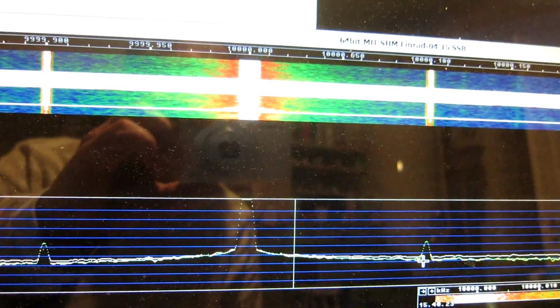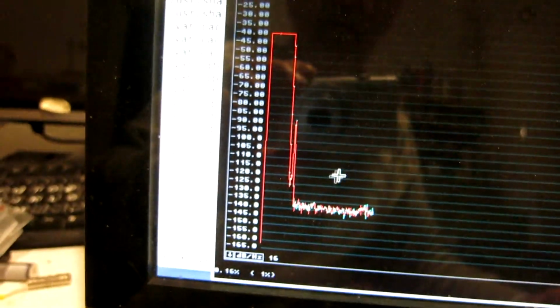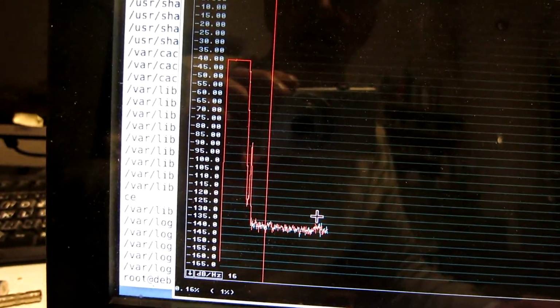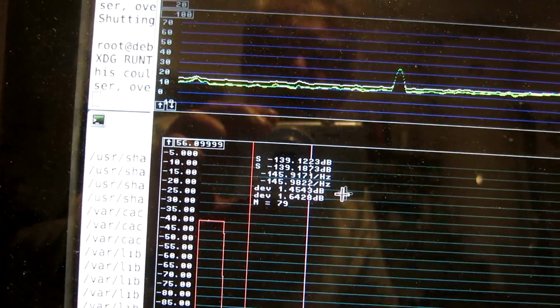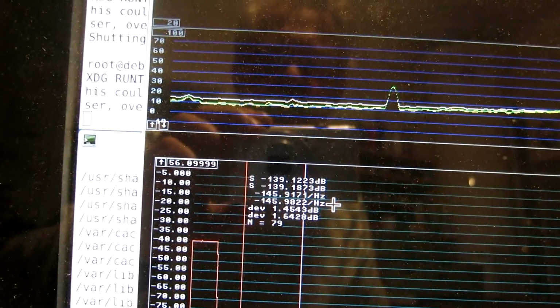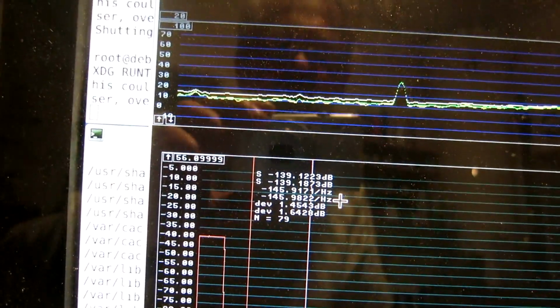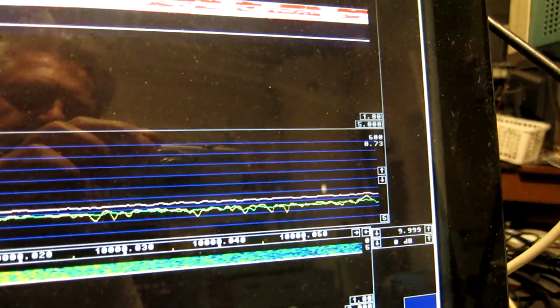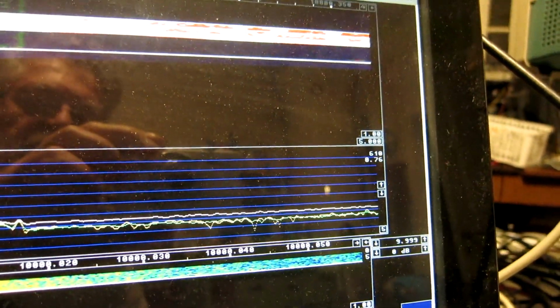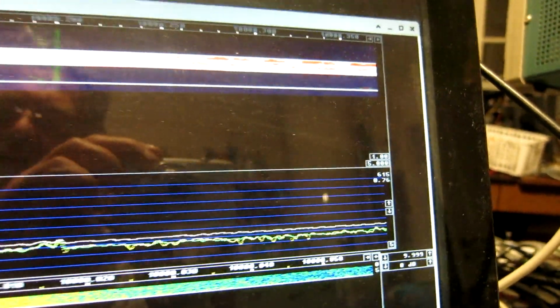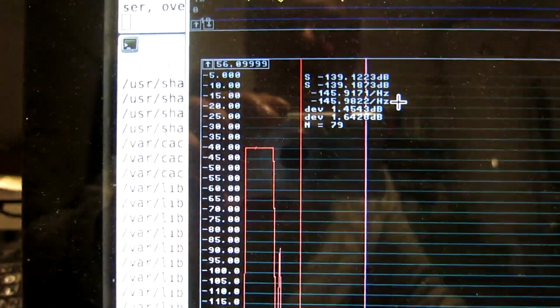So the offset is 25 Hertz, and this one, the properties is I have minus 145, well, minus 146 dBc per Hertz, and the correlation advantage is only 0.7 dB, so it's not much to take into account.